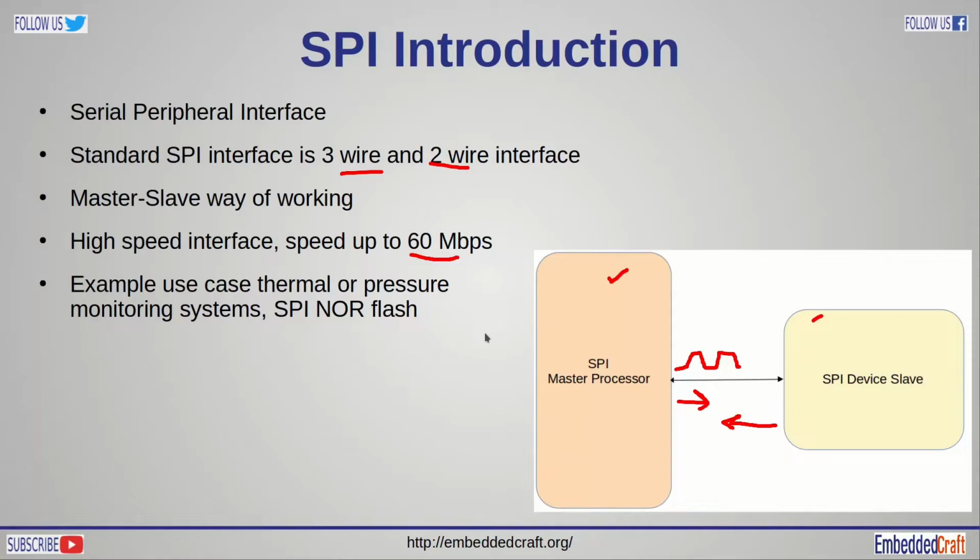Now the question may be where the SPI interface is used. Many sensor chips have an SPI interface, for example thermal monitoring and pressure monitoring systems. And SPI is also used in NOR flash interfaces.